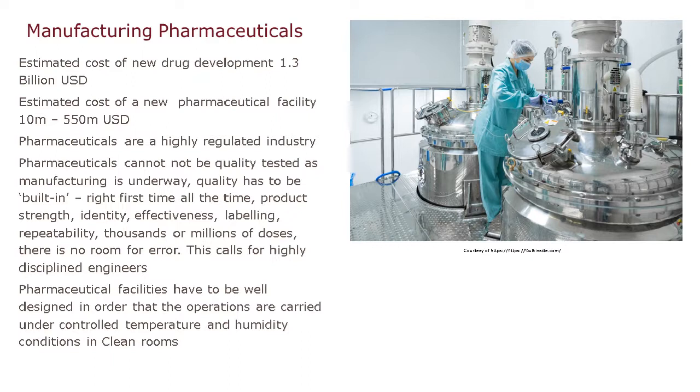The facilities have to be well designed, so the operations are carried out under controlled temperature and humidity conditions in clean rooms. The rooms have to be designed so the operators are comfortable and they don't make mistakes. They've got plenty of room to move around, and they know where to go and start things. There's a picture of, I think, a mini fermenter there, and that's an agitator. As you can see, a lot of stainless steel is used.